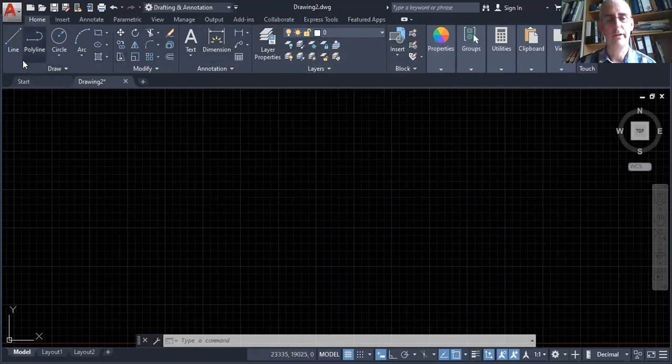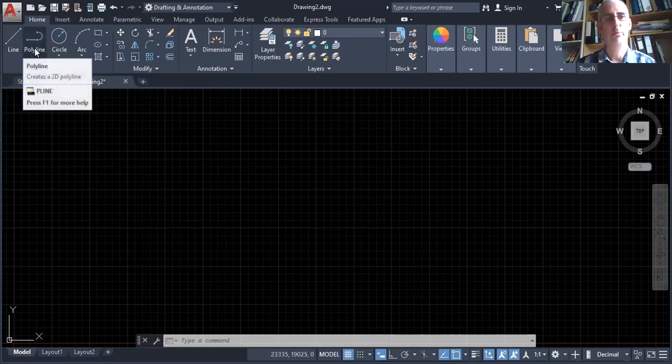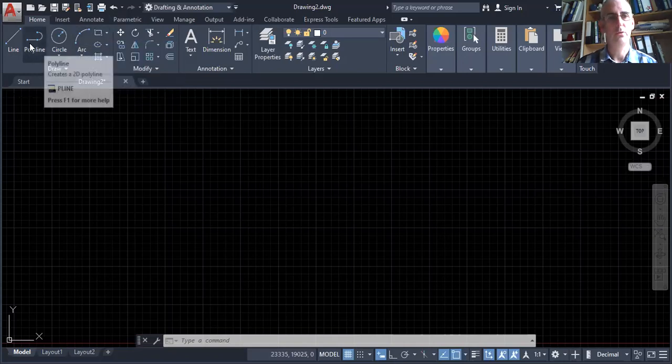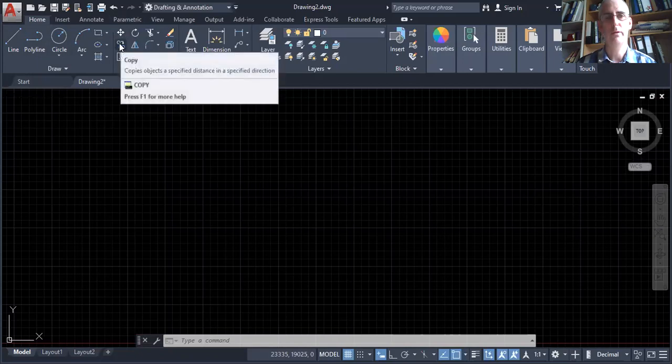And you've got various toolbars, various functions that you'll use quite frequently. As you expect, the most frequently used one is up here with the line commands: polyline, circle, arcs, rectangle. So we're going to be using that quite a lot. And then secondly, just as frequently is going to be a lot of these editing commands up in the modify part of your ribbon.